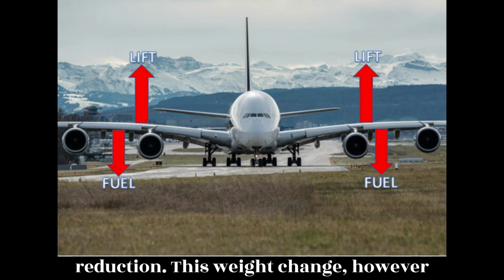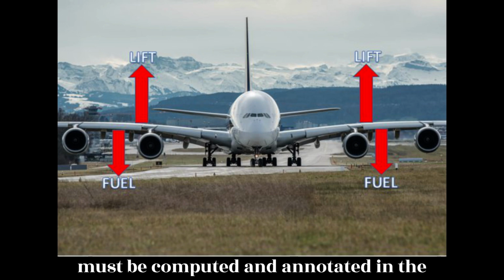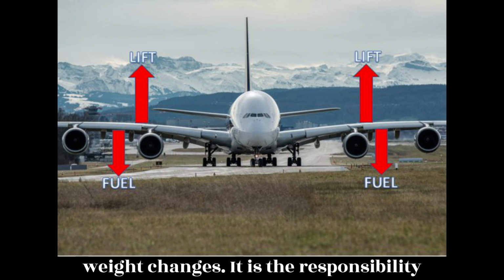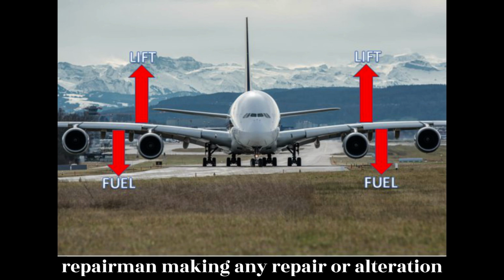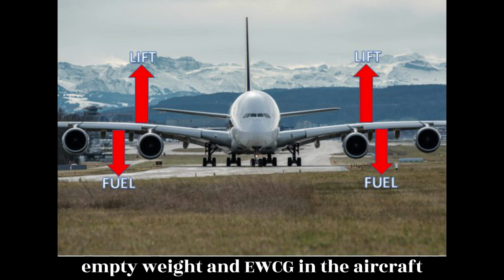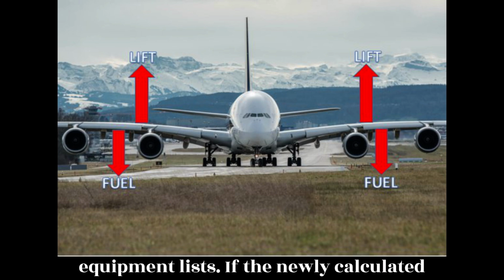Fortunately, the replacement of older, heavy electronic equipment with newer, lighter types results in a weight reduction. This weight change, however helpful, can cause the CG to shift, which must be computed and annotated in the weight and balance record. Repairs and alterations are the major sources of weight changes. It is the responsibility of the FAA certificated mechanic or repairman making any repair or alteration to know the weight and location of a change, to compute the CG, record the new empty weight and EWCG in the aircraft weight and balance record, and update the equipment lists.